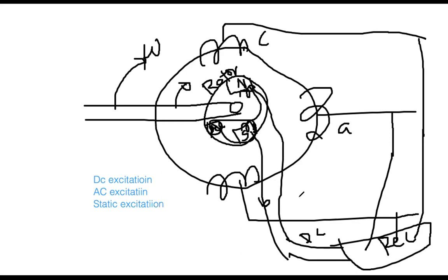Now the challenge here is that this part is moving and the rectifier portion is static, but you are giving the voltage there. That's why you need a slip ring here and you need the carbon brushes. The brushes are fixed, and the slip rings are moving and touching the brushes. Consequently, you are able to provide the DC.